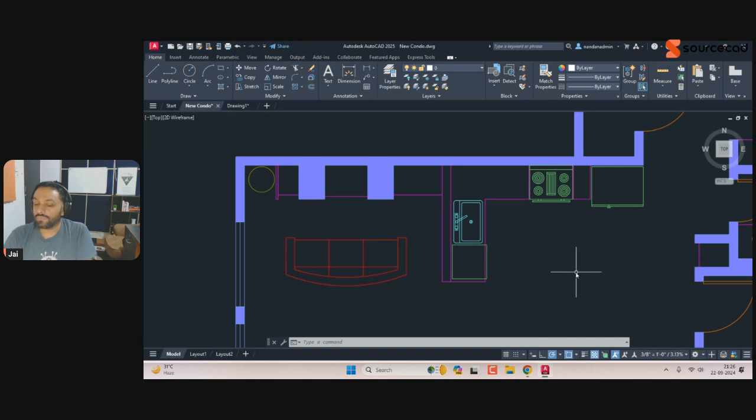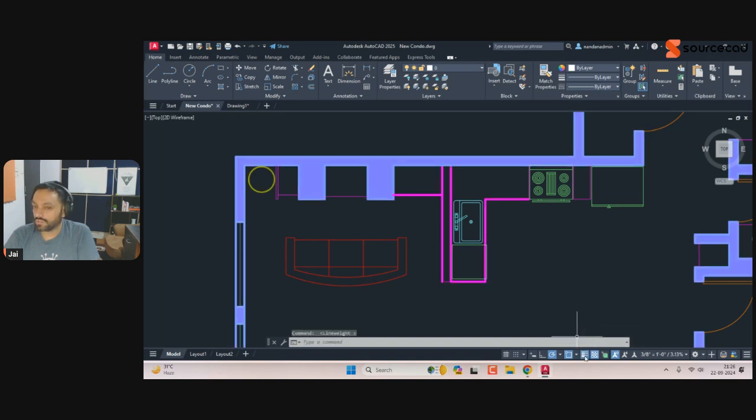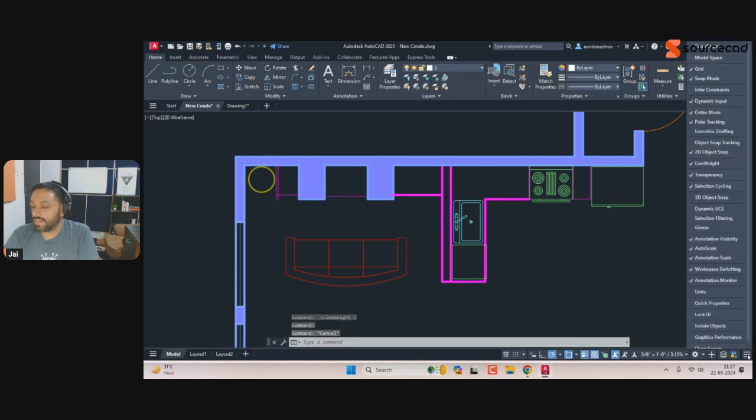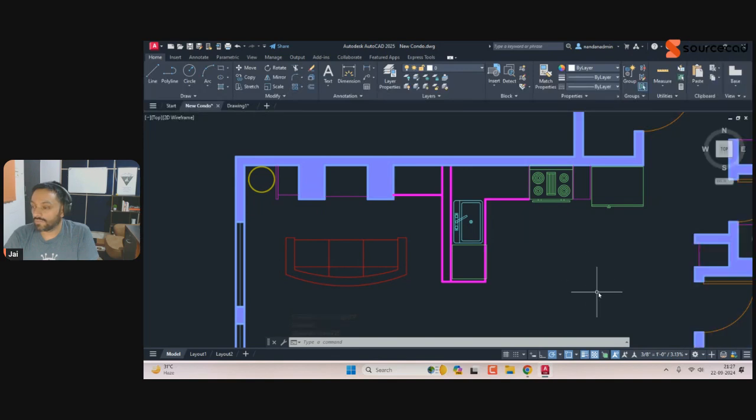All right, now, as this line weight is not showing up, it's simply because of this line weight display option. You can just click on this just to toggle it on and the line weight will show up. The same is with transparency. So let's apply transparency now. We have applied line weight. I just missed this one, so maybe I'll just apply it here. Okay. I've applied the line weight and checked this option, line weight display. By the way, if it is not showing up, go to this three dash line and activate line weight, and then it's going to show up.